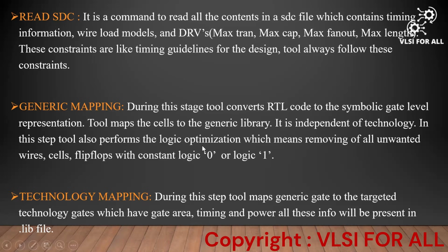In this step, the tool also performs logic optimization, which means removing all the unwanted wires, cells, and flip-flops with constant logic 0 or logic 1. So additionally the tool performs logic optimization, which removes all the unwanted cells or wires. That comes under the optimization that happens in the generic mapping stage.